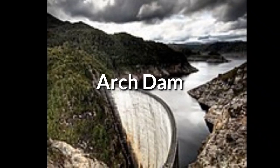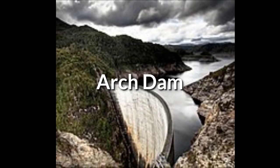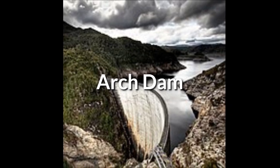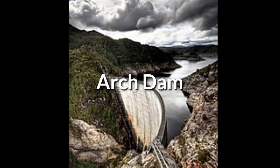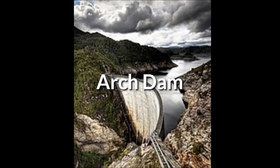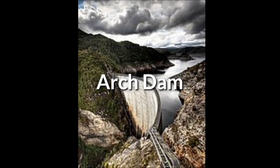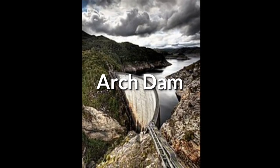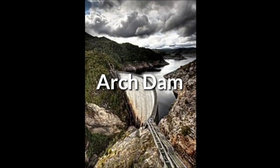This arch dam must be built on solid rock, as a yielding material could cause the failure of the dam. An arch dam is designed so that the force of water, such as hydrostatic pressure, can be resisted. Edge pressure against the arch causes it to straighten slightly, so it pushes into its foundations or abutments. An arch dam is most suitable for narrow gorge sections with steep walls of stable rock to support the structure and the different stresses.